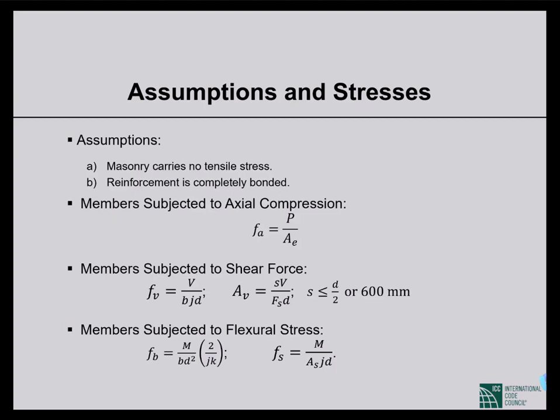And the second assumption is that reinforcement is completely bonded with the masonry through grout. This assumption is not perfect, but we take care of the imperfection by lowering the allowable stresses in both reinforcement and masonry.